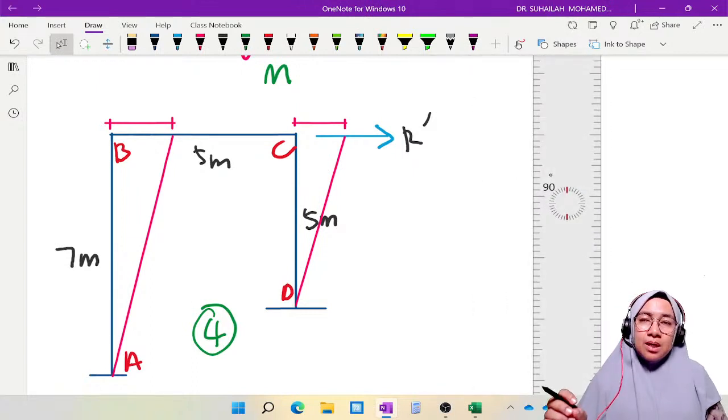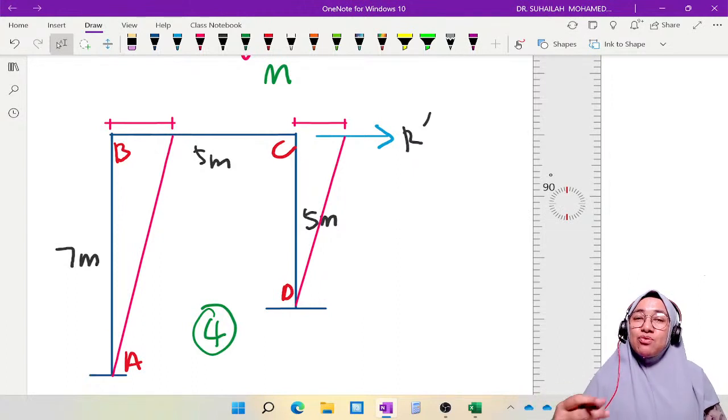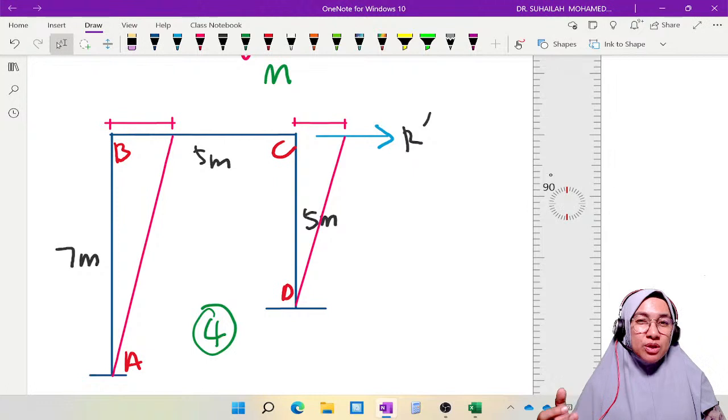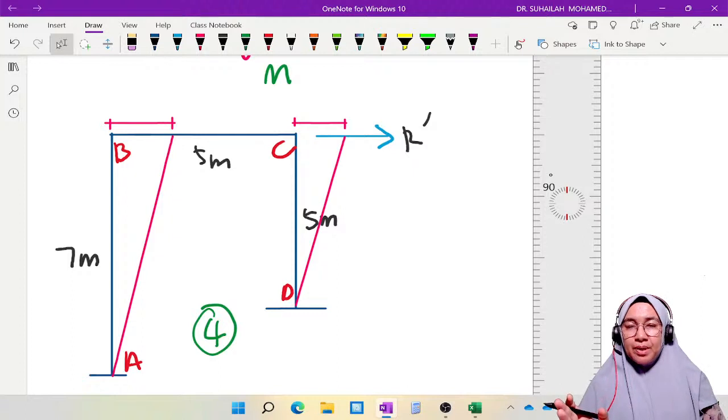Because FEM itself reflects the behavior. FEM due to loading, when we calculate FEM, the moment direction reflects the reaction at the end point to counter back the bent beam to its original position. So in side sway frame, due to delta, the column moves to the right or left direction.